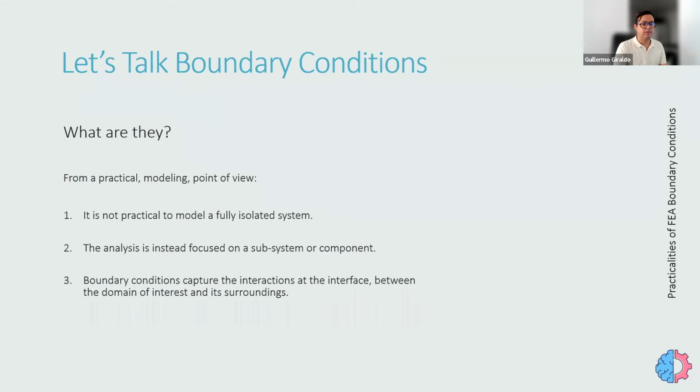All that it means is the time variation of the effects, or the loads, that are imposed on or acting on our system from outside our limit. Boundary conditions, the supports or the loads, and everything: all of these are actions from something that we leave out of our model, but that interacts with our model. So anytime we identify such an interaction, we need to create a boundary condition.